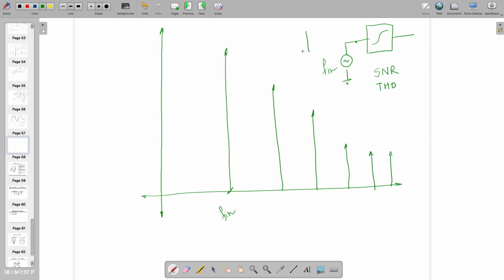Once you are getting the input as just one beam and others are at minus 300 dB, then you should use the same settings and check what is happening at the output. Look, only the input is getting amplified or attenuated on the basis of the slope or gain of your amplifier, and the others are the harmonics. So this is known as second harmonic, this is third harmonic, fourth, fifth, sixth, and you should check till where you are getting minus 300 dB.